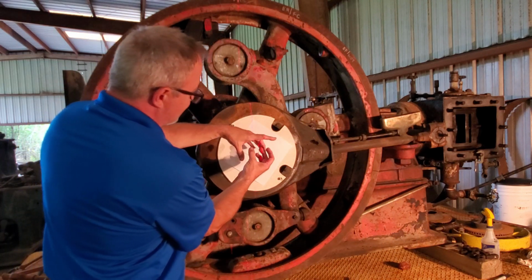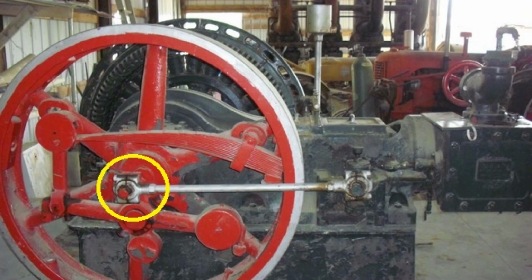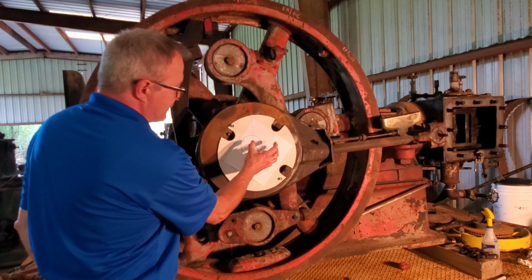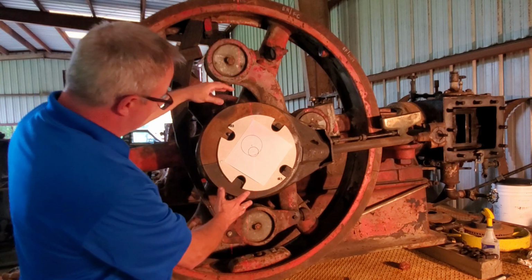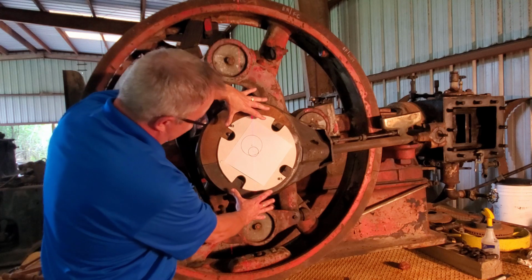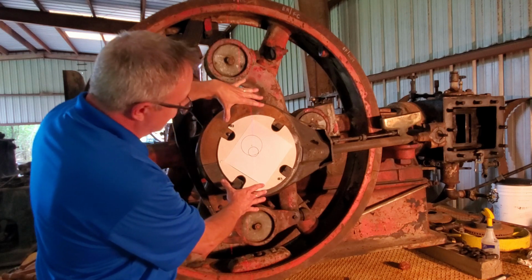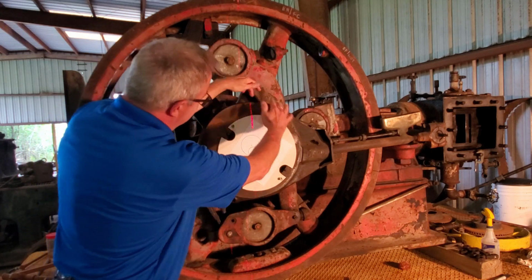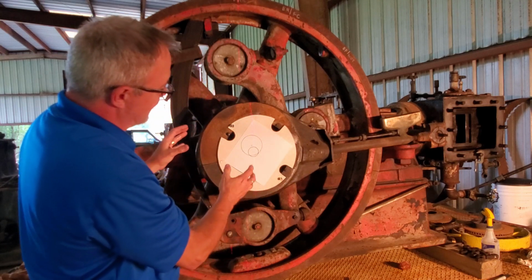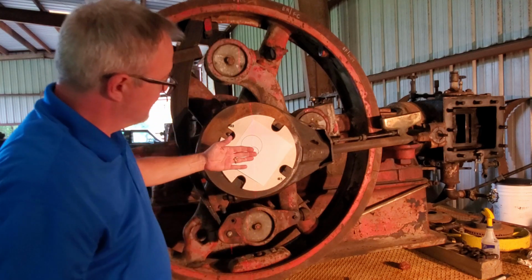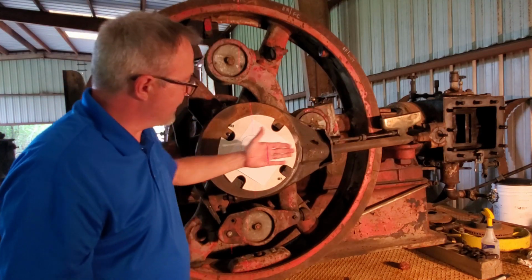It just has a spherical stud out here with a little mating female spherical seat. It does not have this huge, ungainly journal that is babbited, and it has a split bearing cap that traps against that, and it's actually spherical because this is not a straight line motion.